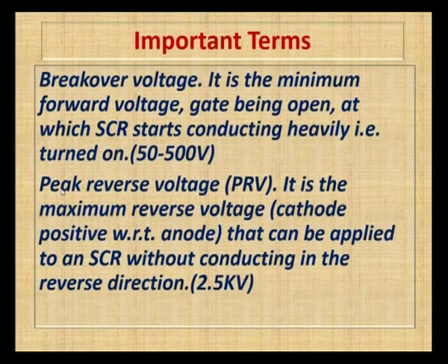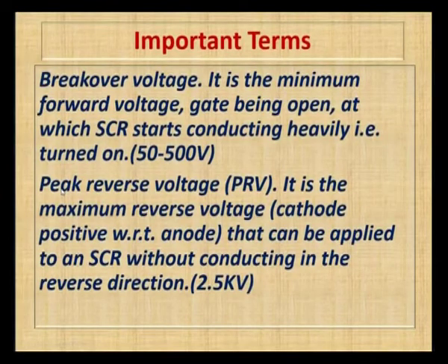Another one is peak reverse voltage. This peak reverse voltage plays a very important role, since the SCR is going to be used in an AC circuit. So, there will be a positive and a negative cycle. In the negative cycle, we should not have a peak inverse voltage greater than the reverse voltage.